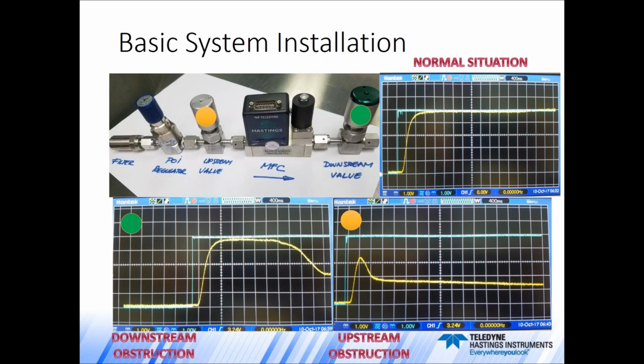What's going to happen is the moment we deliver a set point to the flow controller, and I'm pointing you towards the lower left green marked graph, we'll have the flow controller almost achieving full scale, but then very rapidly the flow decreases till it hits the limit of flow that can go through that downstream small orifice that is represented by a malfunctioning downstream valve.